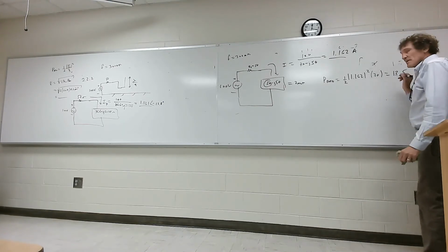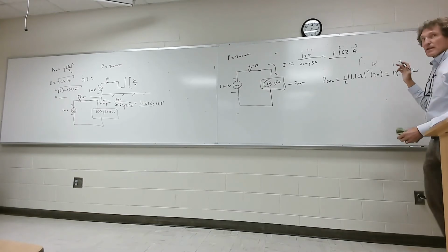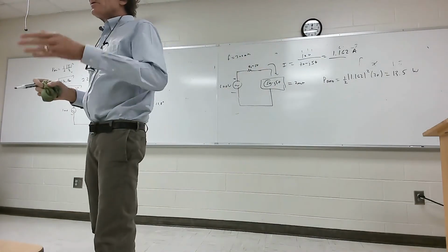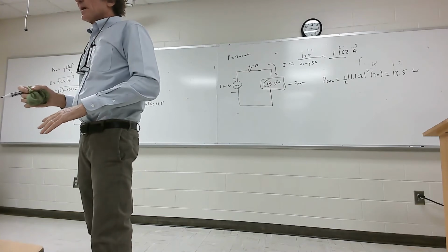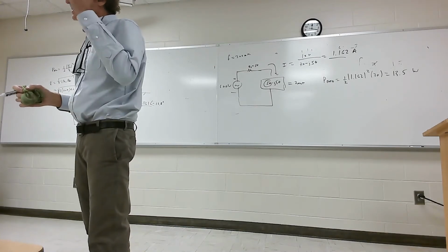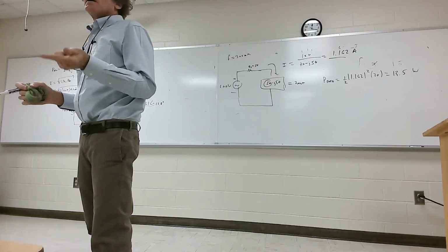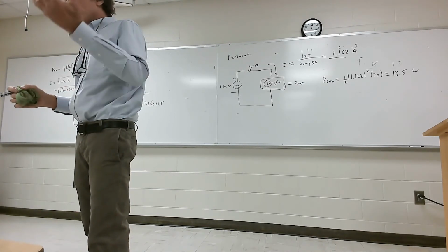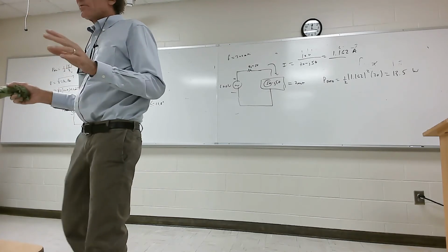13.5, you say? Is that right? Is that the answer? All right, does he ask anything else in that one? If you go through, you can knock these problems out one by one very quickly if you understand this. That's the only thing you have to get: the current and what the radiation resistance is, and you can get the power rating. If you know the directivity, you can get the actual electric field, or really the power density or the electric field, easily, and it's always the same.